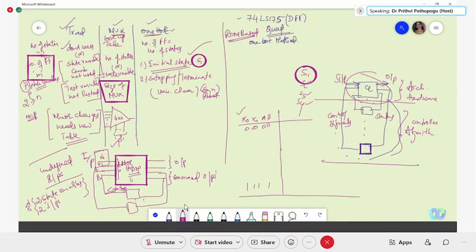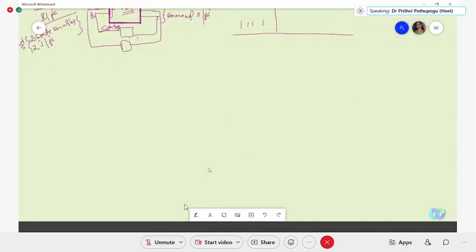In ROM you define the address location, and in that address location the data is already stored, which will be taken out according to the combination of inputs. Whereas in the other approaches we need to define the hardware. ROM is simplest, but the only time-taking issue is defining the table. So how will we be taking this? Say, let me take one simple ASM.